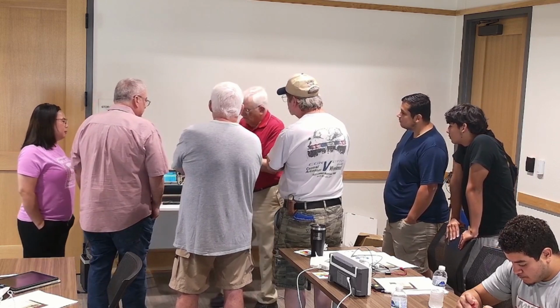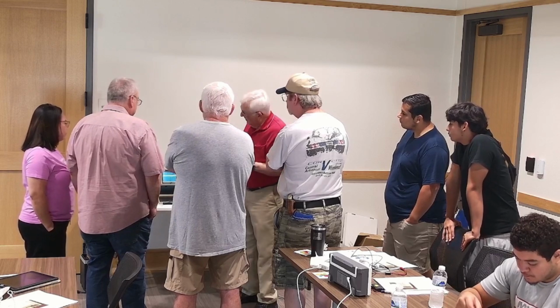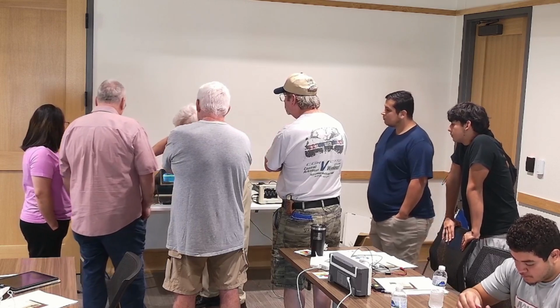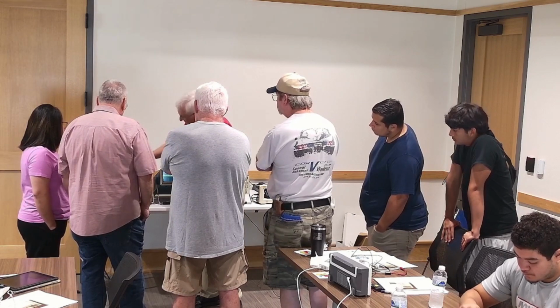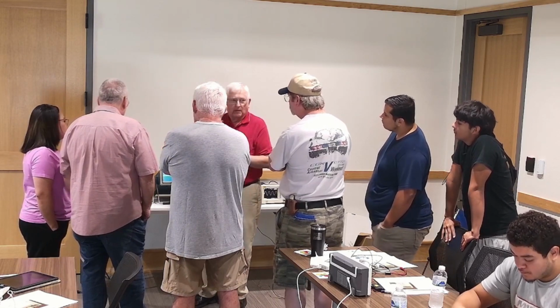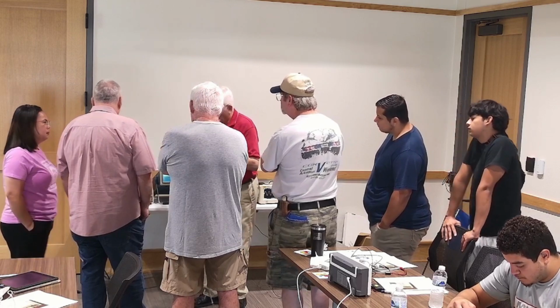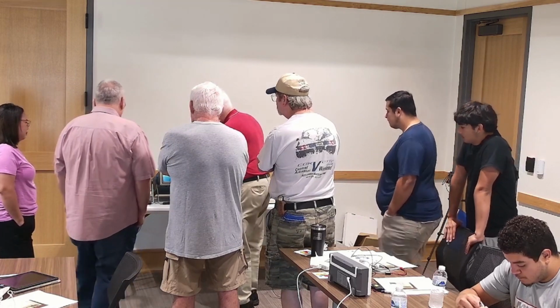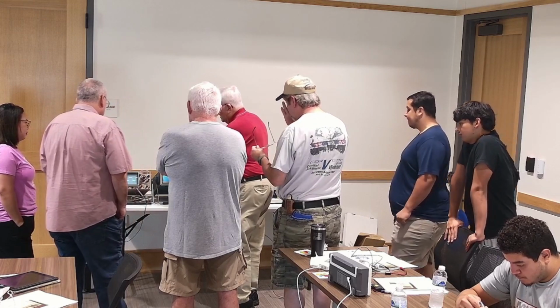Notice there's a little screwdriver opening inside there. If this probe is not compensated correctly, not set correctly, then you get this rounding that you see right there. So I can turn that little screw and make it a nice, solid, square wave. I can compensate for that to make it nice and square. That one obviously has not been compensated. But that's kind of the idea behind it.